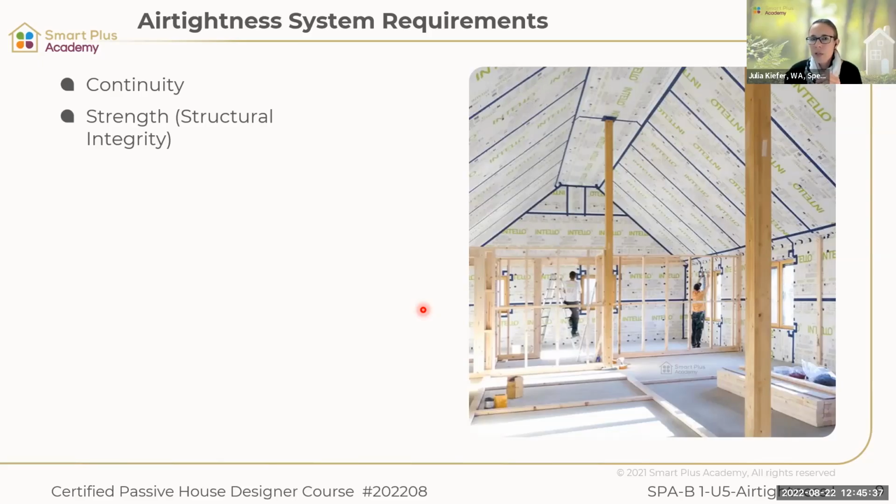And in reality, if a storm's coming in, you want that system to withstand that storm as well. Okay, so it's unlikely that it goes up to 50 Pascal, but this is what we're testing it for, and that's what it needs to be strong enough for. It needs to be durable, and it needs to be airtight, so air infiltration, impermeability. Obviously, that's what we want to reach. Good. And here's an example where they've used a membrane for it, but we don't have to use membrane. We can use other materials as well for airtightness, which I will introduce to you in a second.